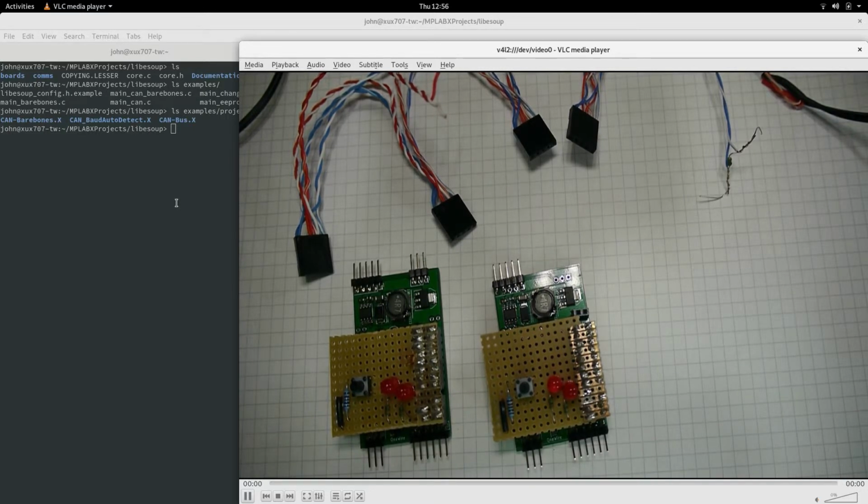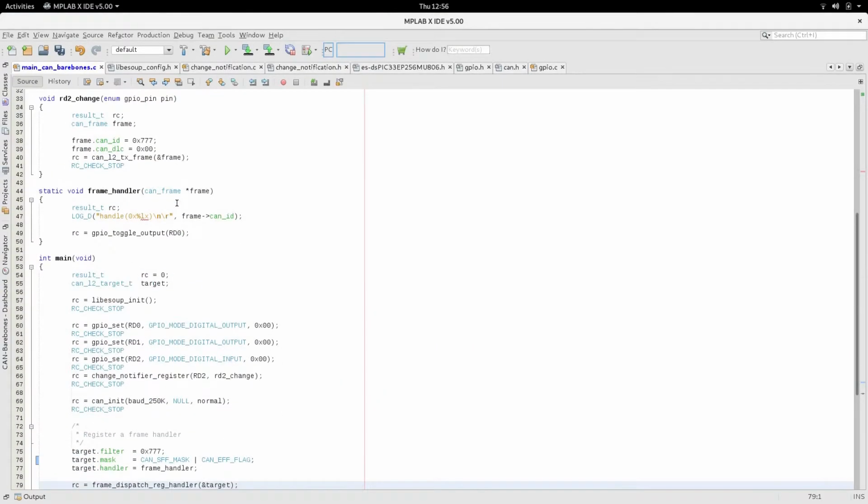So as I said, Modbus is address and command. CAN bus does not have addresses. Now, even though I talk about CAN at layer 2, so CAN bus layer 2 transmits a frame, the OSI 7 layer model, which I discussed briefly, layer 2 of that standard specifies that a frame contains a source and a destination address.